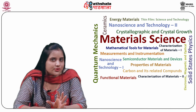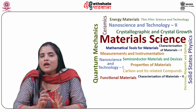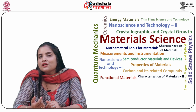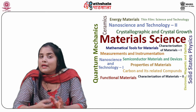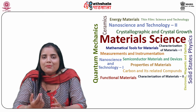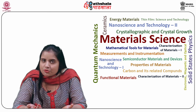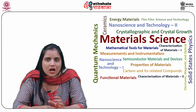A quantum dot solar cell includes a mesoporous TiO2 layer as the backbone of the cell, which is similar to a dye-sensitized solar cell. This layer is made photoactive by depositing quantum dots over it via chemical bath deposition, or electrophoretic deposition, or successive ionic layer adsorption and reaction.